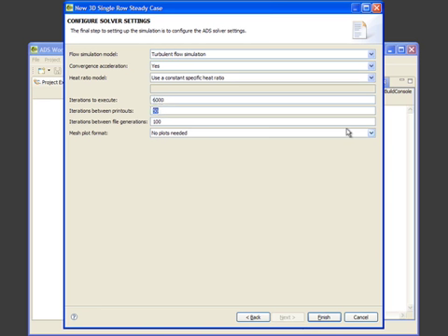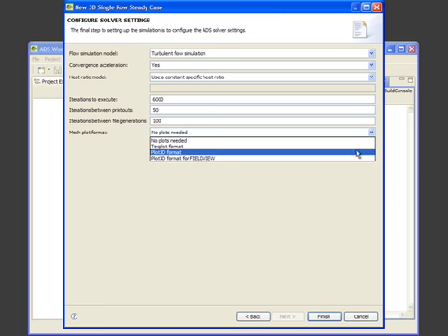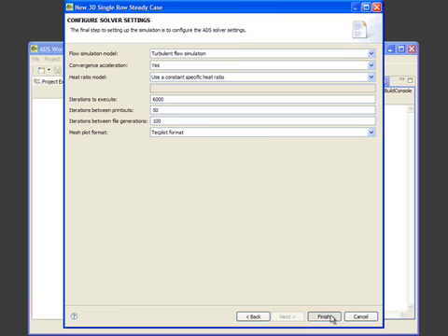You also have the ability to determine when printout of performance data occurs. We've decided to print it out every 50 iterations. And also you can specify the iterations between plot file generation and restart file generation. Here we've defined it as 100 iterations. You also can plot out all the performance data into one of many plotting formats. We'll pick Tecplot for now. And you're finished.